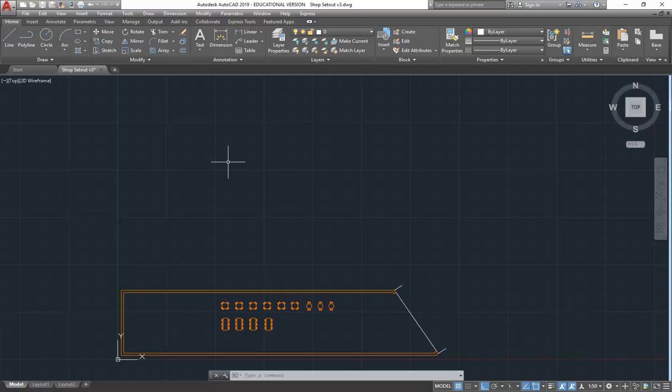If you do the plans and then the elevations, you can't always then go to do the sections because you won't have enough information to do the interior heights. But if you've done the section, then normally you can get all the heights for the elevation. So that's normally the way you do it. Plans, then sections, then elevations. And you'll see that comes up.